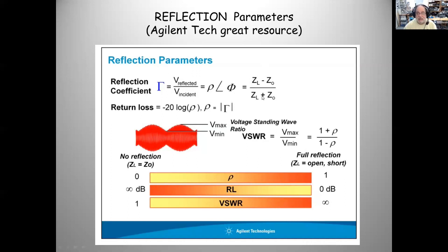But if you take a value and take its absolute value, you get something much simpler called the magnitude, or I'd call it the absolute magnitude of the reflection coefficient, and that's called Rho. That's easy to see. Rho is just a fraction from 0 to 1. Couldn't be any easier. It's simpler than SWR. Reflection coefficient has to do with what's coming back on the feed line from the antenna back towards the radio, or your NanoVNA, compared to what's going forward. It's just a ratio. It could be 0, could be 1, or anything in between.